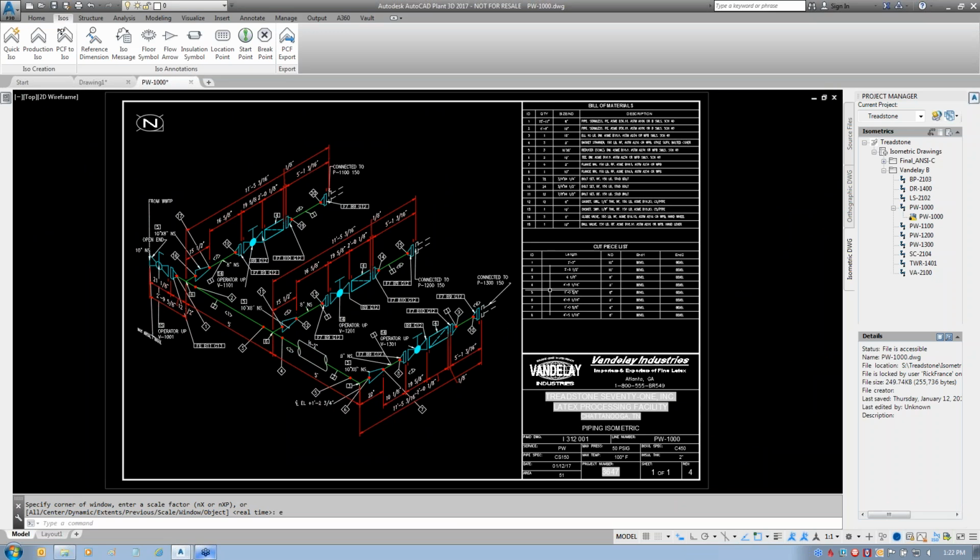Any other questions? But how much insulation? I'm not sure what you mean there. Are you talking about how many feet of insulation or things like that? I mean, the size of the diameter, the thickness of it, is their extent. That would only be shown if you put that in. It's not going to show it here on the isometric. You would have to put that information on the piping drawing. Most likely, once that property is on the piping drawing, you could add that information to like the bill of material or something like that, because you could add that column.